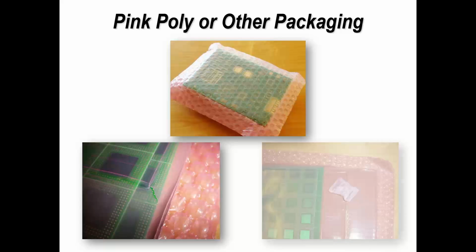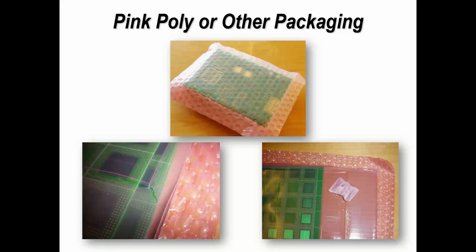So if you were to get boards like this, where you've got the boards which are shrink wrapped in plastic, the desiccant and or the indicator strip is completely separated from the boards but sealed within the plastic with the plastic around it. What value is that? Absolutely nothing. So again, think about what's actually happening. Is it a value? Isn't it a value to you? Because it's not actually been used correctly. I'm not saying I see this too often, but I'm just making the point.